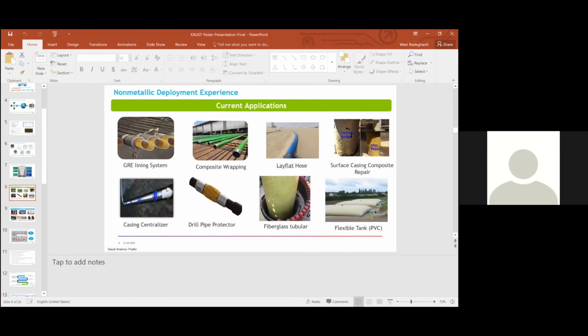Then in the design stage, based on modeling and prediction, we are going to select the type of other fiber, either glass or Kevlar, which is a very good fiber in terms of energy absorption. So it's the first candidate, and for the strength, carbon fiber is the other candidate.